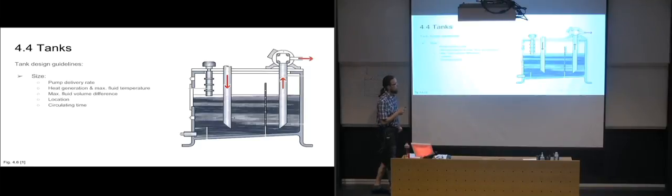And then, of course, the circulating time. So how much time do you need from the fluid being returned into the tank before it gets sucked back into the pump? So the size of the tank will have something to say there, because you will have a minimum distance that it will have to travel and a minimum speed that it will have to have.